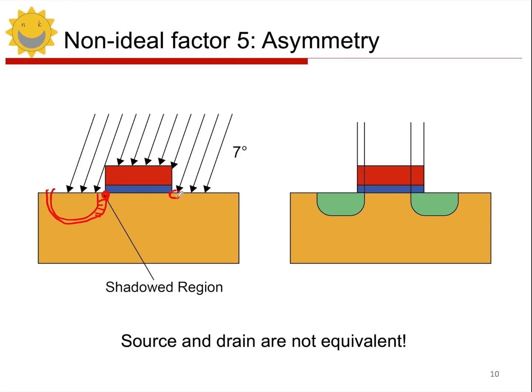So, as we can see, after the entire processing, the two implantation regions are indeed different. For example, the overlap of the source and the drain with the gate is different, so the parasitic capacitance is different. This leads to the source and drain of the device being different, right? The source and drain themselves are not the same.